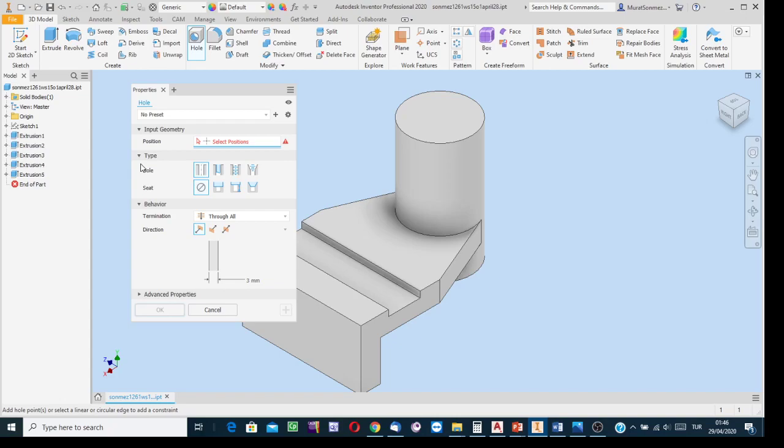You remember, it was some weeks ago, I talked about the hole creation tool. I said that after clicking the hole creation button, then in the dialog box, if you select this type option, this means it is a non-standard hole. Customized tool, and then into this box write the diameter. If the hole is a counterbore hole, select this option. Countersink hole, select that option.